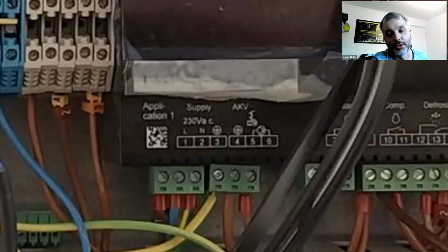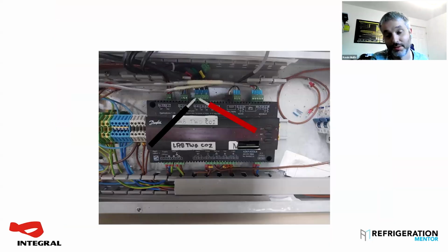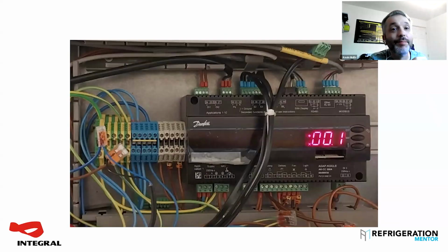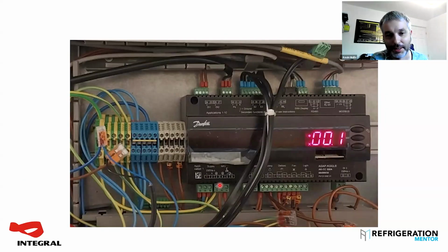If you've got a voltage out to the coil and you're still not doing any cooling, then you're going to be at the coil end going, has my coil burnt out? You can take the coil off, do a continuity test on the coil. The exact value isn't really important. It's going to depend on what voltage your coil is, but you are going to want to see some resistance between the 2 pins. If it's dead short, you'll probably find it's damaged the controller. But if it's open, then your coil's not going to work.